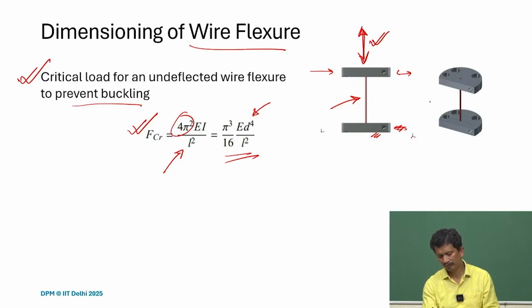One thing is that when you are working with these small diameters, it's very difficult to assemble. So for that we made these slotted features here, and you can see a slot and a hole here, and it's assembled with a screw here. We use this threaded screw and we clamp it from there. So these are some small features, and we have to take care of that.